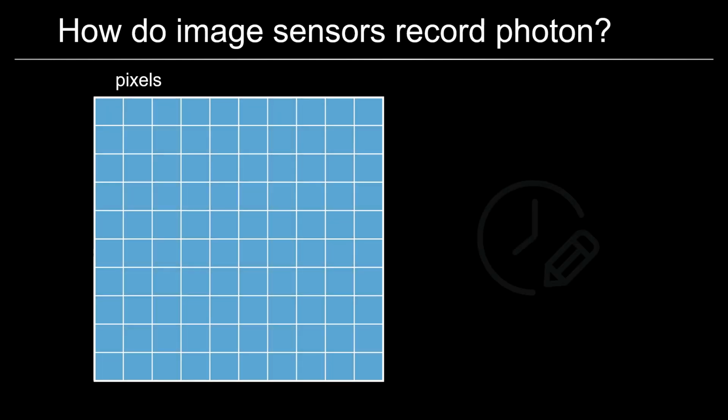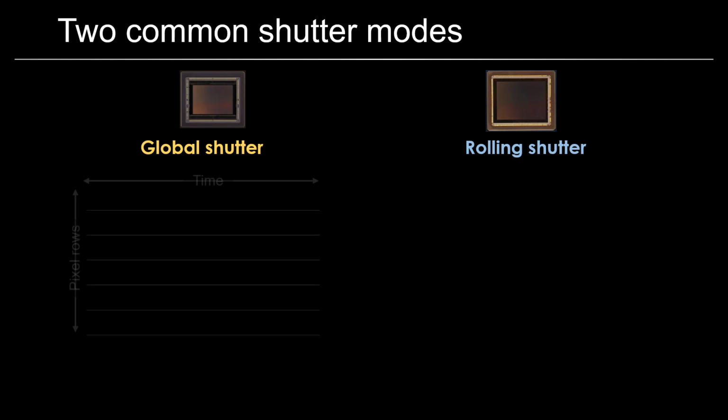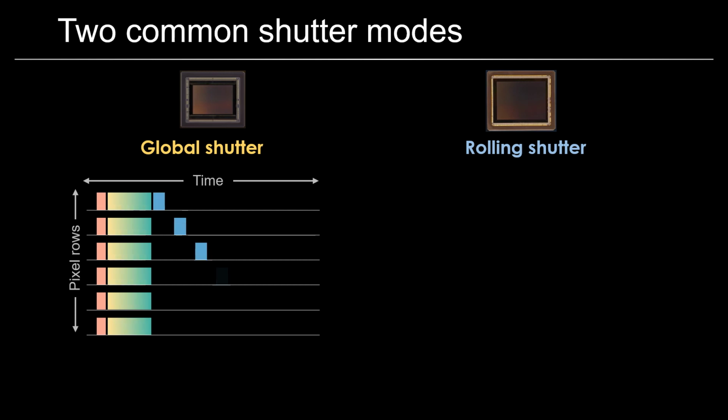A key design of image sensors is scheduling the exposure time and readout time of different pixels to reuse limited readout circuits. This scheduling function results in two different shutter modes: global shutter, GS, and rolling shutter, RS. GS-based image sensors expose all pixels simultaneously and transfer accumulated charges to a storage area before readout. But the requirement for additional storage increases their cost and leads to more noises.